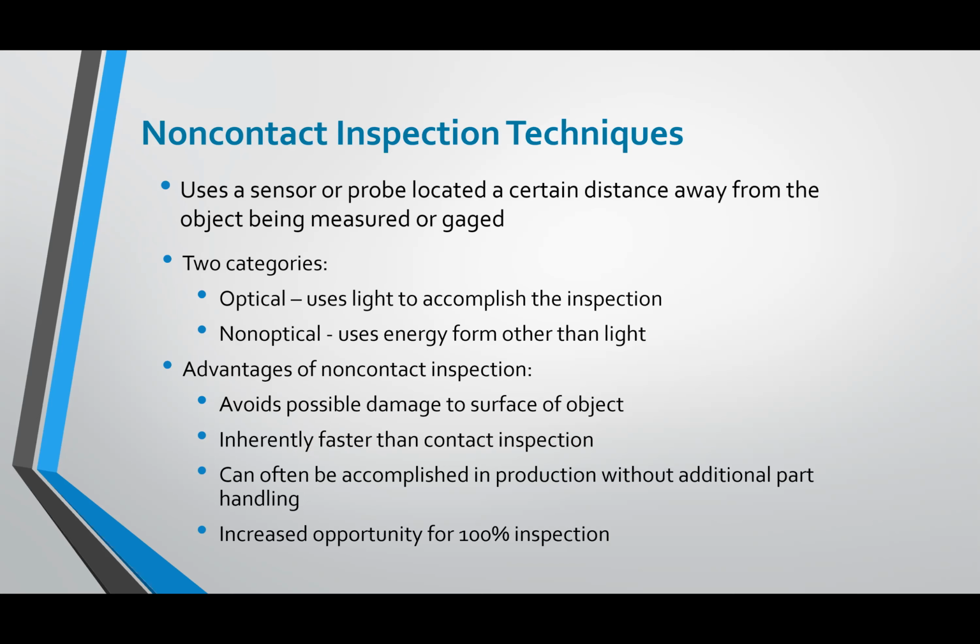And when you look at vision systems, it's going to show you a couple different optical sensors that are measuring height, width, presence or absence of a certain component, a fill rate of a certain item. All of those things can be done, and you can have a 100% inspection at the rate of production without ever taking anything offline. And then the only product that's segregated is product that's found to have a defect.